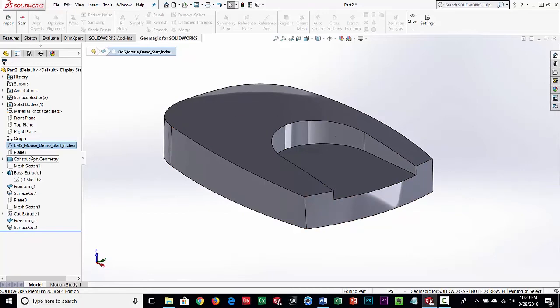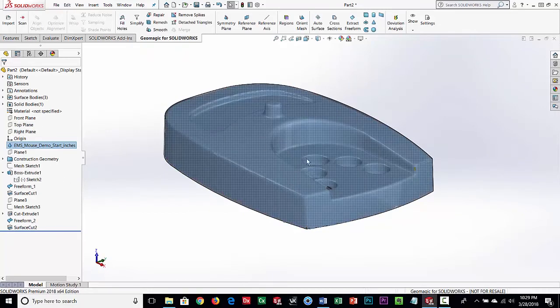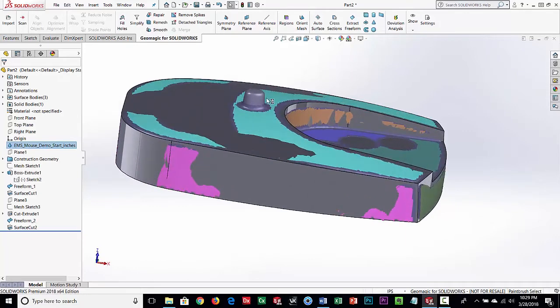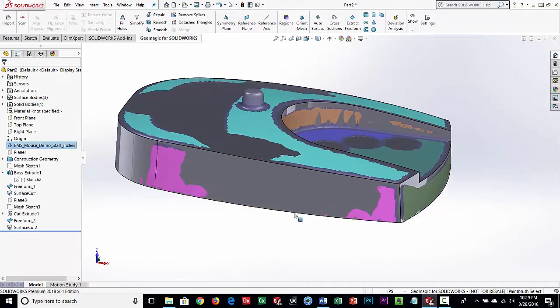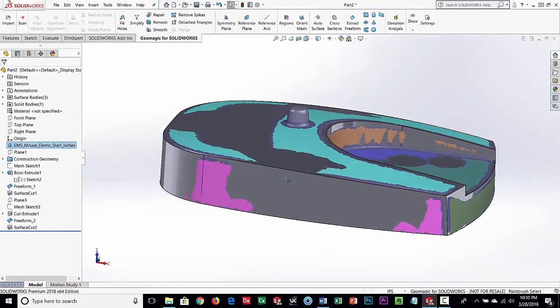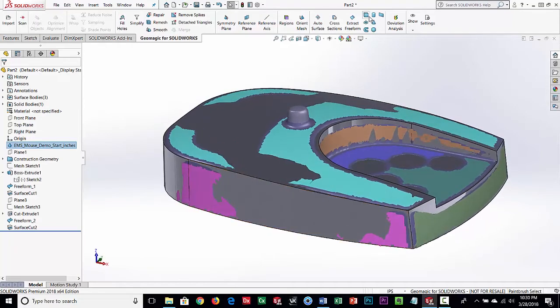So let's go back to the scan data, and on the top here, I've got either a cylinder or a cone, and one of the things we can do is we can extract different shapes from scan data. So a lot of your primitives, spheres, cones, cylinders, planes, even some basic sweeps and rotations you can actually just extract from the scan data, and primarily again those region groups.